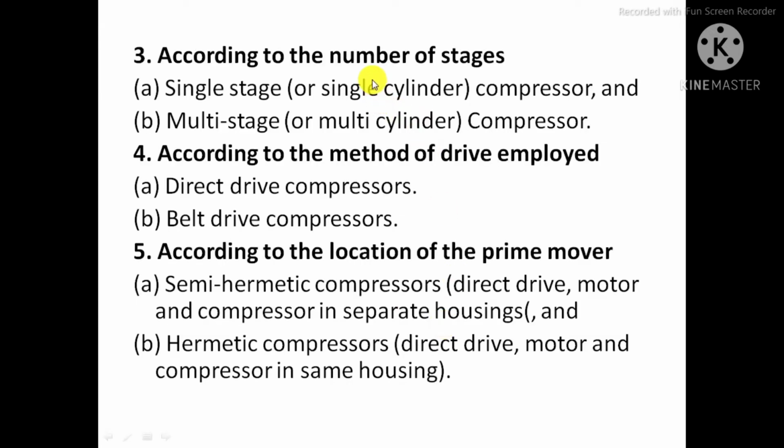The third way is according to the number of stages, so we can have a single stage compressor or a multi-stage compressor. A single stage compressor is generally used where the pressure ratio requirement is low, but a multi-stage compressor is used where we need a higher pressure ratio.